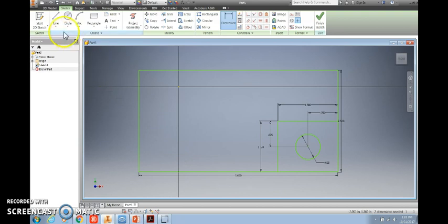All right, from the upper left-hand part of the screen, I'm going to select the line. And I'm just going to go ahead and sketch a line from the corner on up to this top edge of the larger rectangle. I also need a line extending out so that I can dimension from it. So make sure that that line is straight and go ahead and draw it right there. And now I'm going to select dimension, select my first line and then the second line.